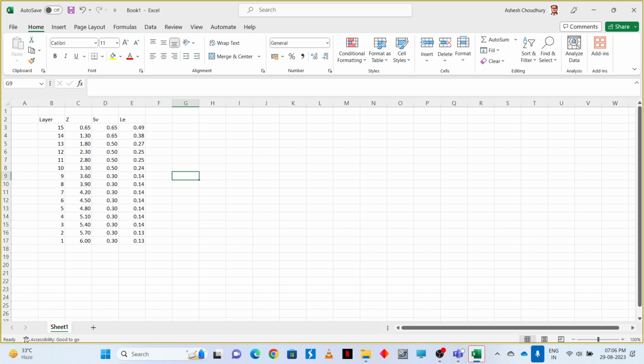Okay, so these are the LE values, but what is the LE minimum? LE minimum, as you know, should be 1 meter. So these LEs are coming less than LE minimum, isn't it? The calculated embedment lengths are coming to be less than the minimum required. So what we need to do is provide this minimum embedment length.